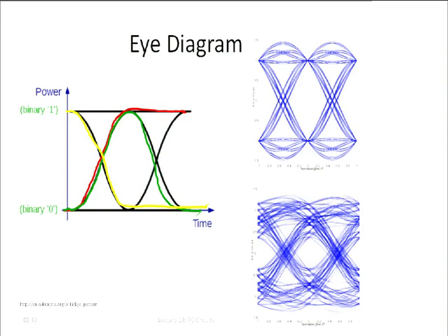So now if you go at reasonable speeds, then whenever the first transition, this is a 1 or a 0 here, and then this is the next transition, a bit could also be a 1 or a 0. If you go reasonably slow, you pretty much reach the desired value at the end of your bit period. But as you start going faster and faster, you don't quite get there anymore. And then these lines are starting to fill in this area here. This area is called the eye.